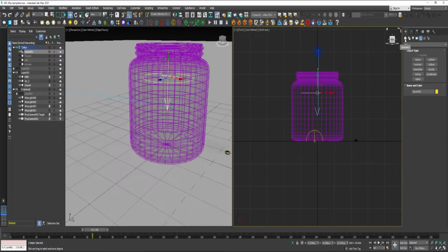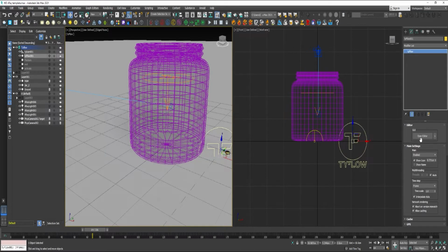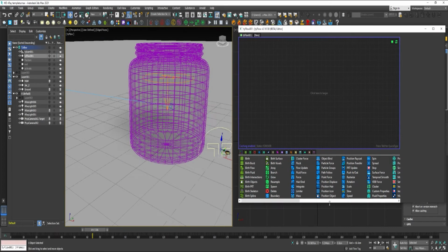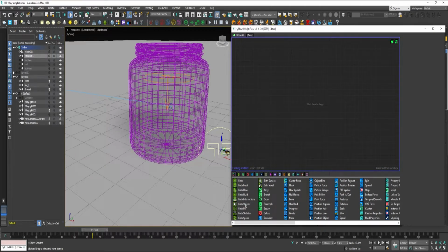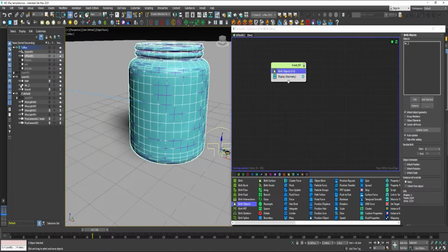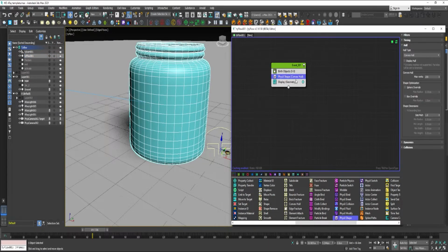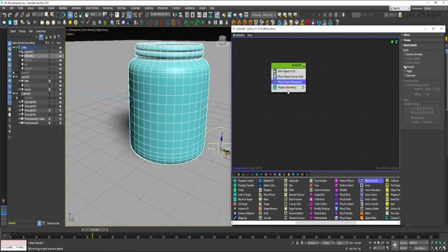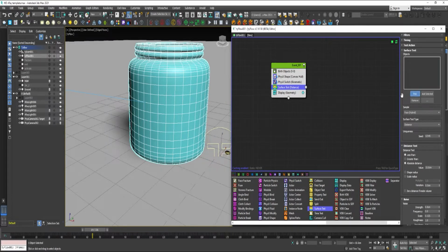We can go over here to Geometry, select TyFlow, go over to Modify tab, Open Editor. Birth objects. Pick the jar and turn the jar off. And turn it into a PhysX shape. We switch to kinematic. Then we will do a surface test. Search for Activate. Change the search type to Shape Radius.